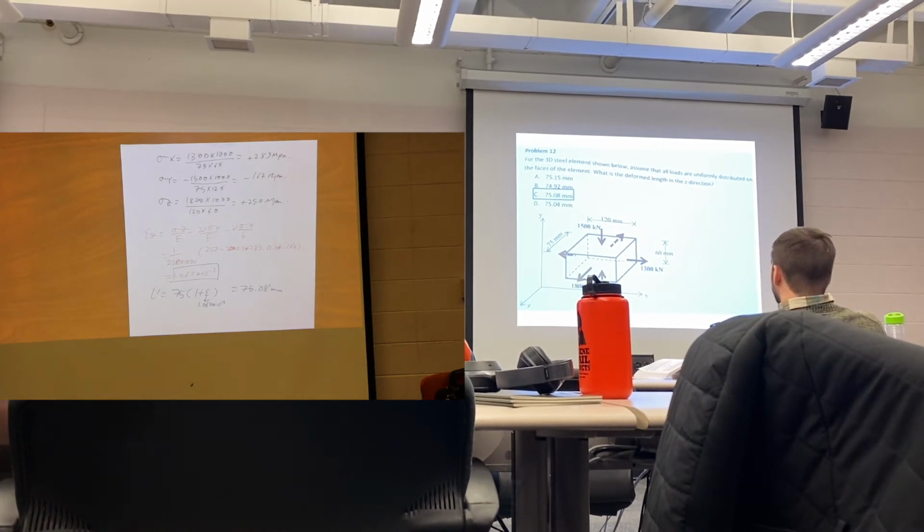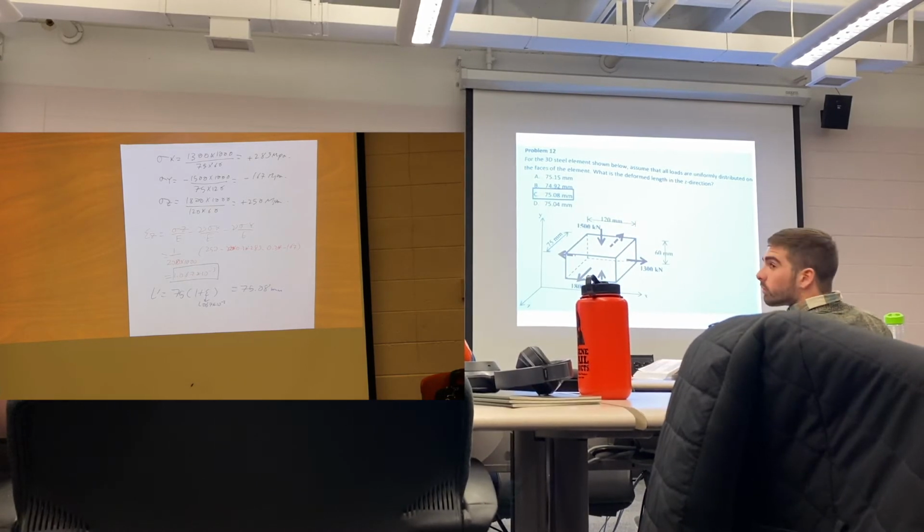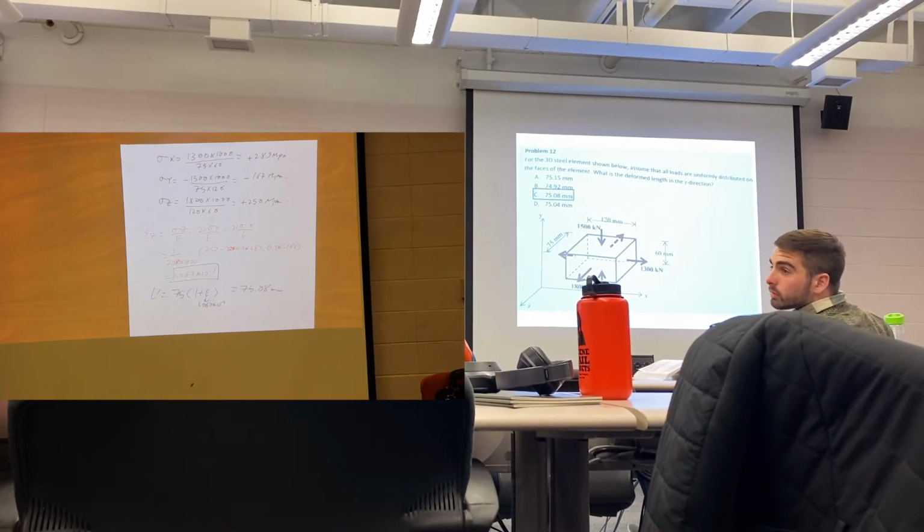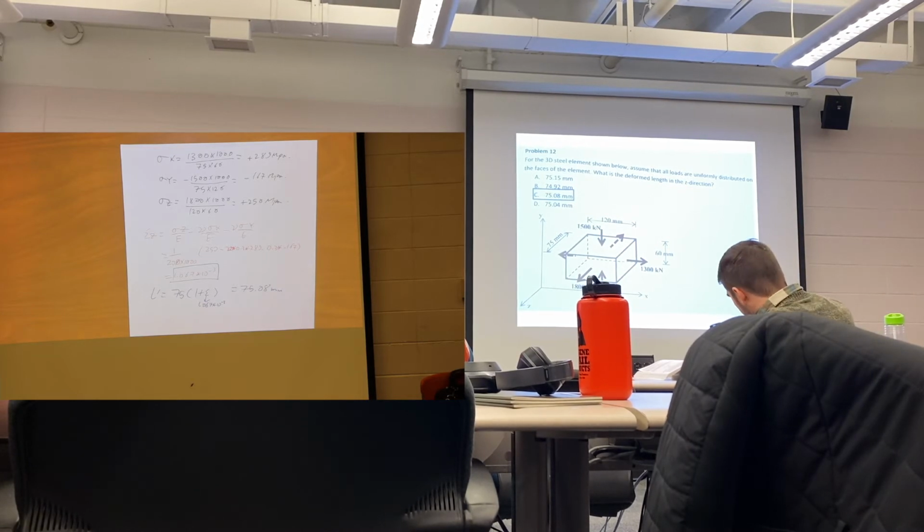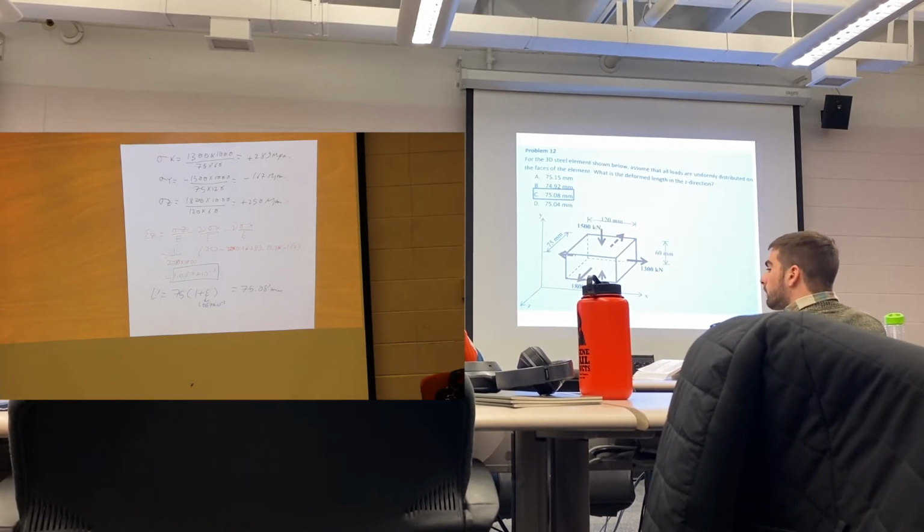This is a bit tedious, but it's just being careful with your numbers. Yes. Could you maybe go over the sign convention of the strain? The sign convention of the strain is like the sign convention of the stress. If compression produces a negative stress, it produces negative strain. So if something is compressed, it's decreasing in length. Tension is positive stress producing positive strain, increasing the length.